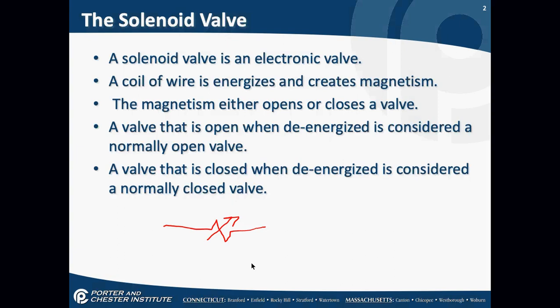A valve that's open when it's not powered is a normally open valve. A valve that is closed when it's not powered is a normally closed valve. So again, just like with contacts, I have normally open and normally closed valves. Normally open valves, if I want to close them, I have to power the coil. Normally closed valves, if I want to open it, I have to power the coil.